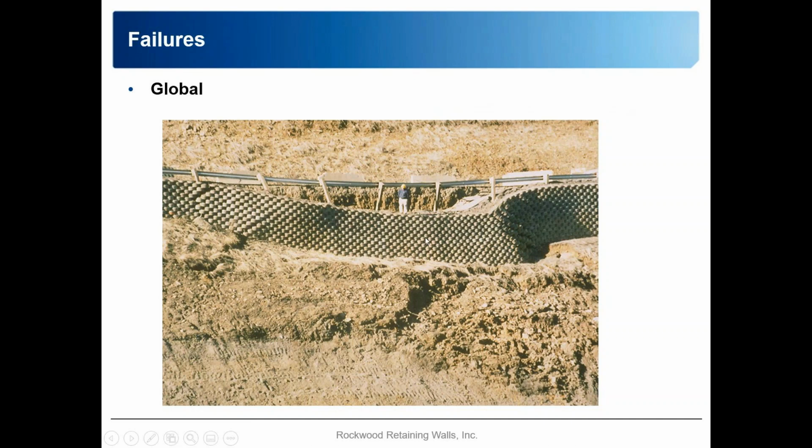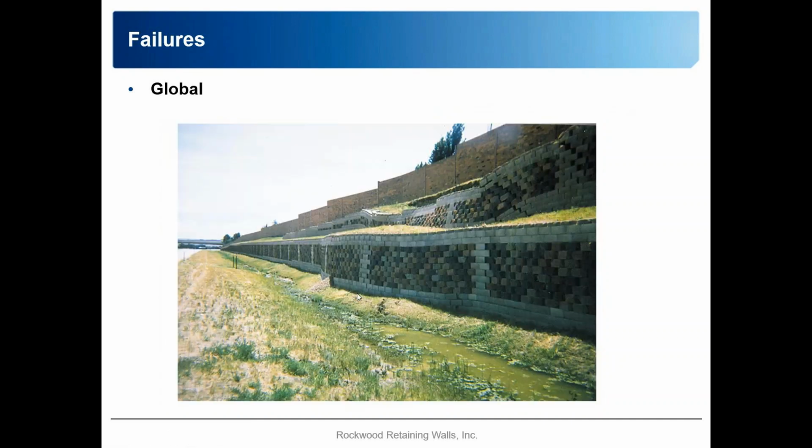And when we put the weight of the block and the weight of the soil, as we do in a reinforced retaining wall application, all of this additional weight that's created not just from the block, but from the additional soil behind it, has pushed down and created this toe slope out in front to fail. So again, walls built on slope, typically we're going to have deeper embedment, and this is just an example of a global stability type failure.